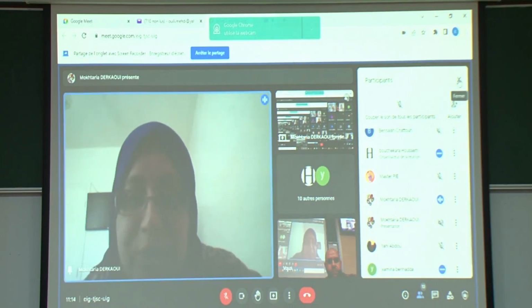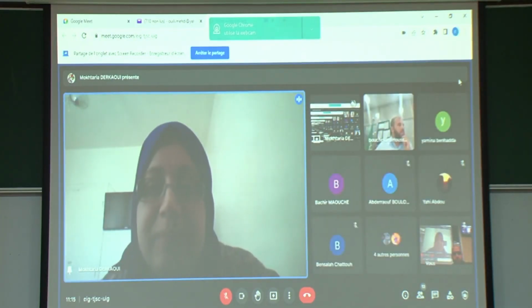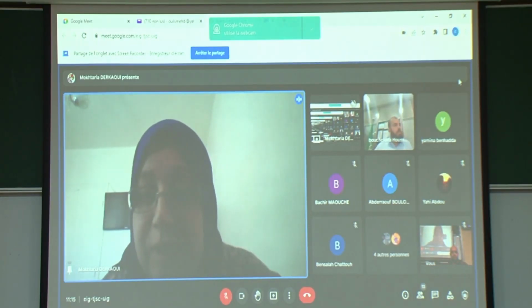For the electrical design of the microtransformer, every layer is represented by a small circuit. When you put the coil in the conductor, this coil will be represented by the inductor in series with the serial resistance, and these two components in parallel with the capacitor at high frequencies.